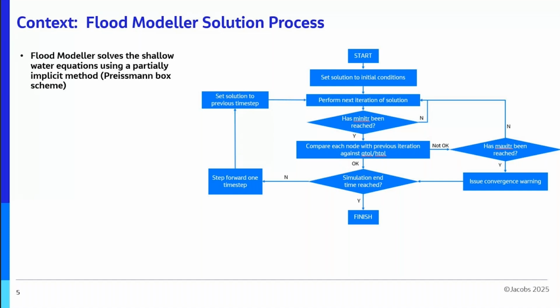Flood Modeler, in terms of the solver, solves the mathematical equations, which are usually known as the shallow water equations when they are reduced to 2 dimensions, and the Saint-Venant equations when they are reduced to 1 dimension. And they do so using a partially implicit method known as the Preissmann box scheme.